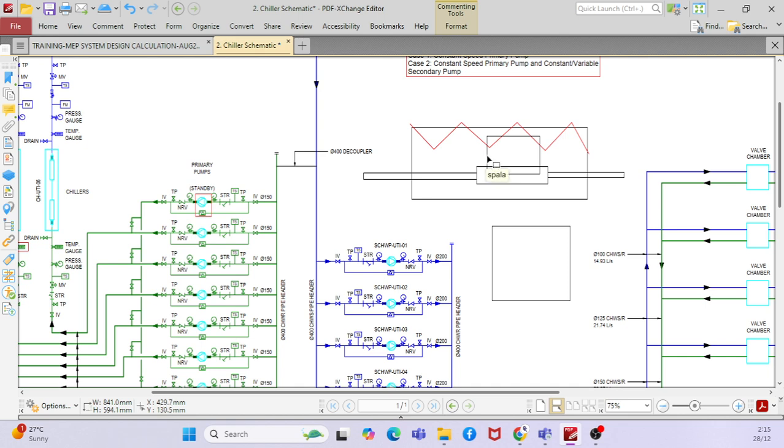So when that heat should be rejected, right? That heat rejection will happen. Say for example if you have an air cooled chiller, whatever the outside air will take out all the heat from the refrigerant. Say for example you have a condenser fan on top of the air cooled chiller, so when the condenser fan runs, the outside ambient air will go through the condenser, take out all the heat, and reject the heat through the condenser itself. So this is the air cooled chiller.